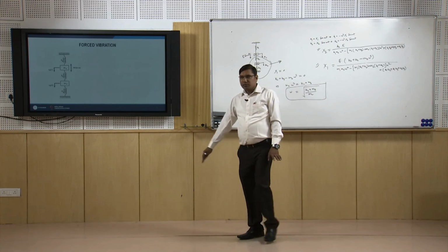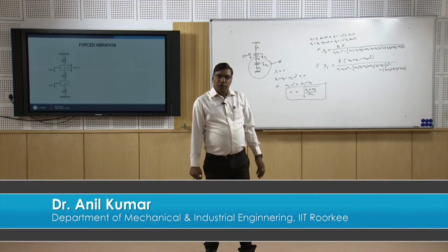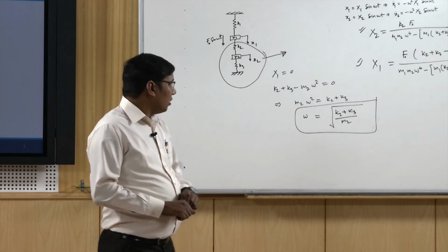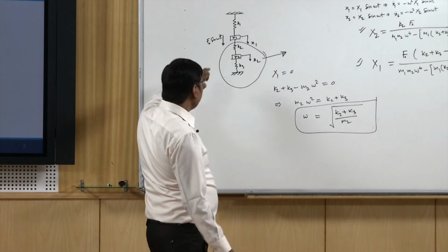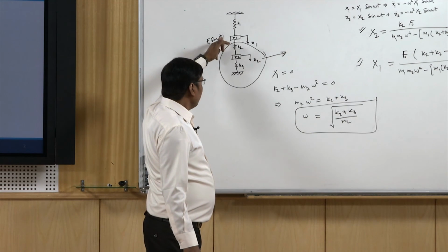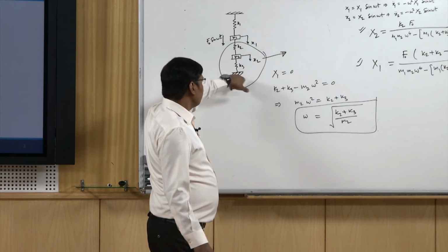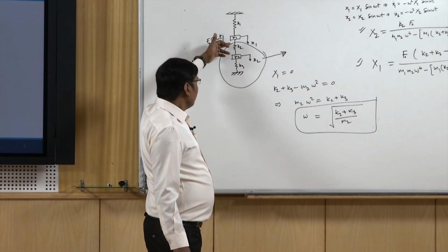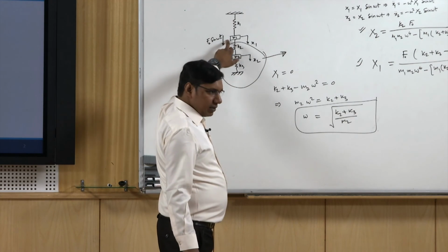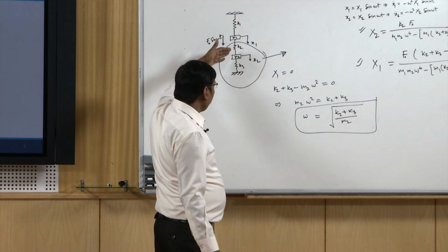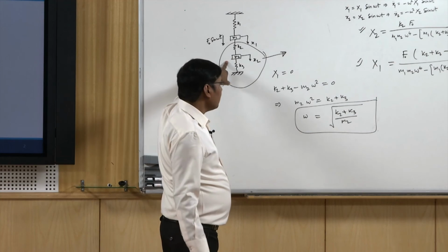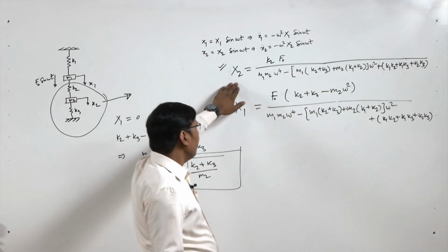So this gives the principle of vibration absorbers that are used for bringing the main system to rest. If some force is coming to the main system, we can select an auxiliary system following this relation, so that the vibration of the main system comes to 0 and that vibration is transmitted to the mass m2, and here we see that the vibration of x2 is not 0.